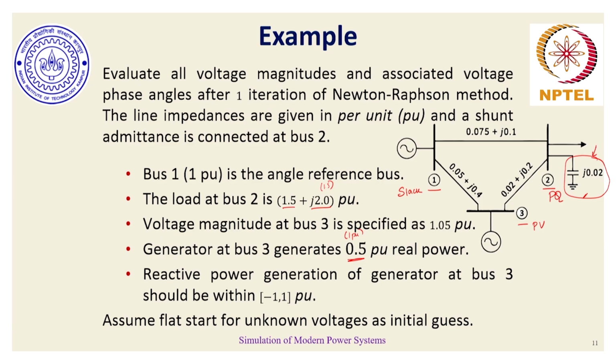If the Y-bus was singular, we have also discussed the implication: if Y-bus becomes singular, the bus impedance matrix cannot exist, and in the initial discussions on power flow we discussed that we won't be able to find unique bus voltage phasors